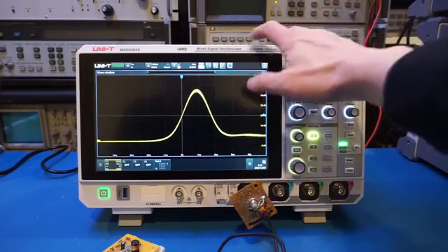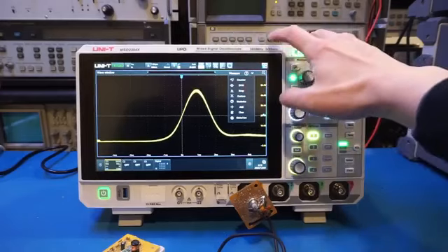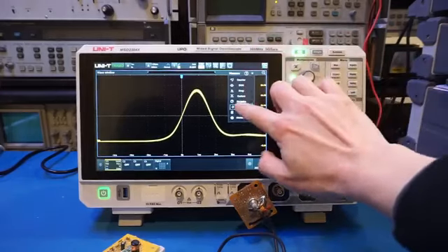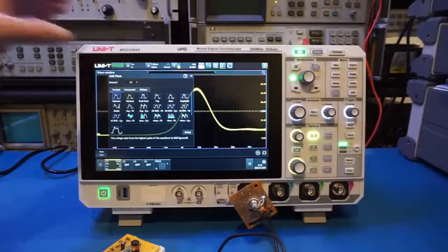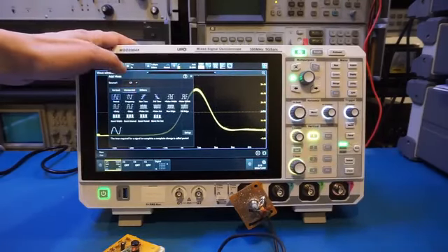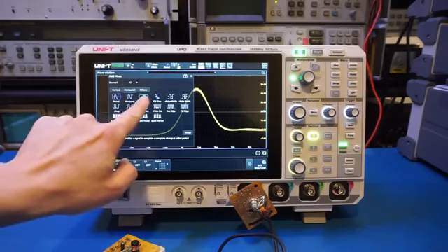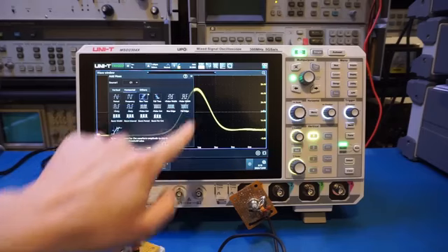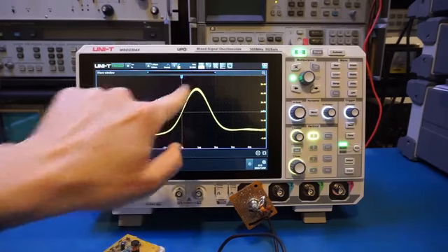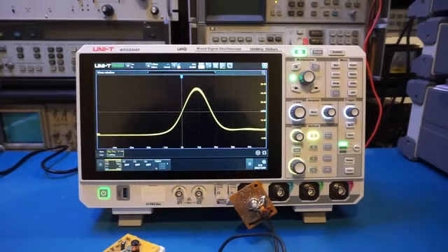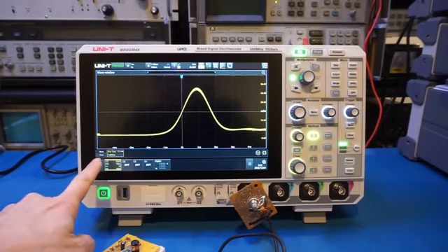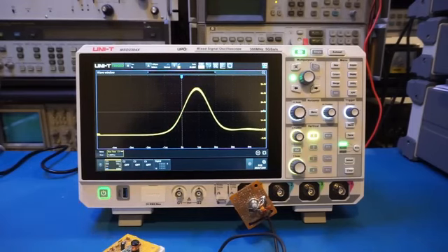So I'm going to choose the automatic measurement. And let's do add. I think it's going to be horizontal. And here we go, rise time. So let's hit OK. The captured avalanche pulse is very, very clean. If you look at the automatically calculated rise time here, it's right around 1.25, 1.26 nanoseconds. This actually put it just slightly under 300 MHz.